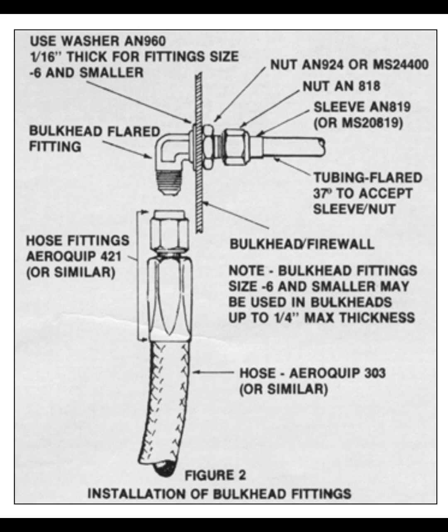Name considerations when installing flexible hose assemblies. Slack, flexing, twisting, bending, clearance, and clamps. What pressure is used to proof test a flexible hose assembly? One and a half times the recommended operating pressure of the hose.